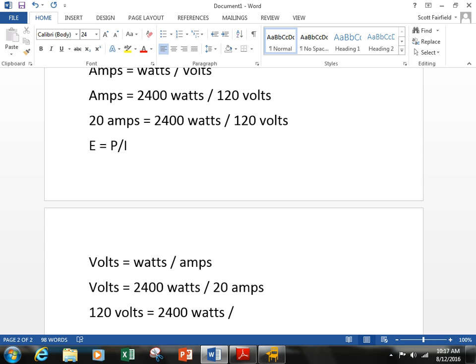If you exceed that, that's where we're going to have problems. In some of the older houses, older wiring, circuits haven't been updated. There may be an incident where the microwave, the toaster, and the coffee pot are on the same circuit, they happen to run at the same time, and the breaker trips. The breaker doesn't trip any other time, but it trips because those three things happen to be exceeding that load.